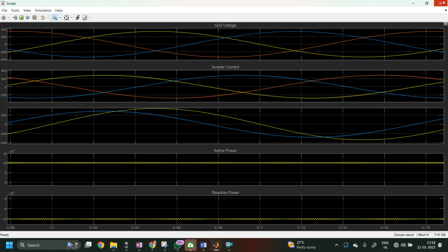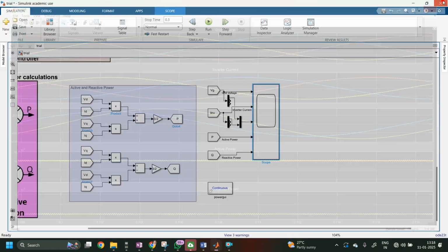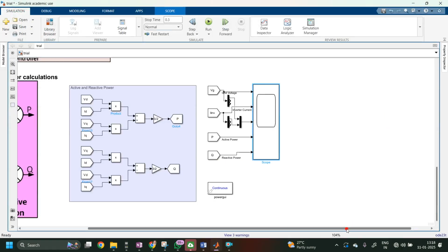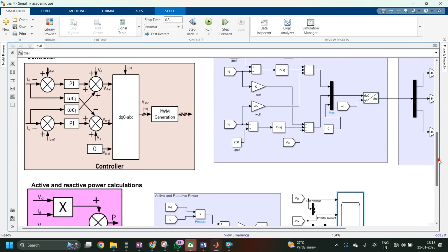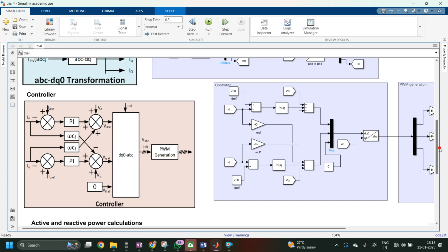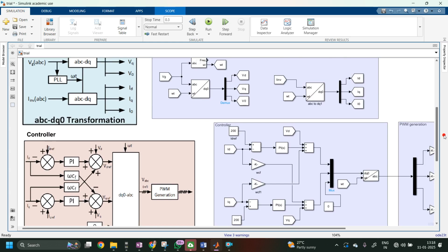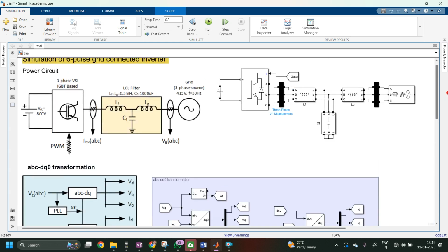So total current is equal to the square root of ID squared plus IQ squared. By this way you can simulate and adjust the current injected by the circuit. You can control the active power, reactive power, or both injected by your inverter. So this inverter can inject active component, reactive component, or both, if the source is a battery source or any DC source of infinite energy.